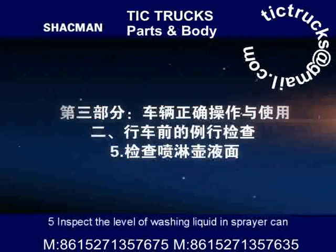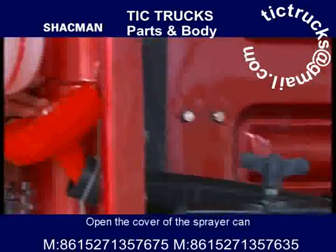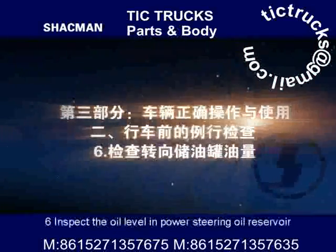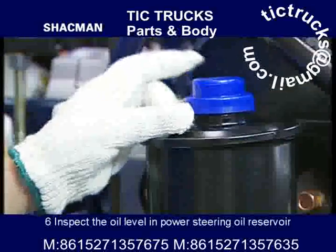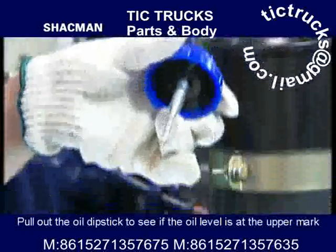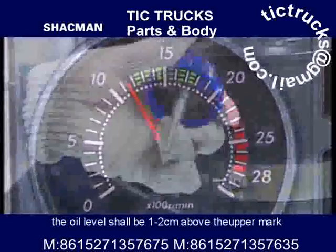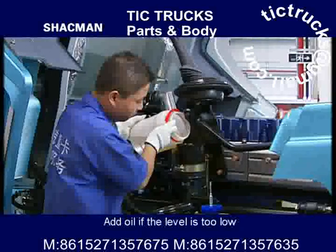5. Inspect the level of washing liquid in sprayer can. Open the cover of the sprayer can, check the level of washing liquid, and add liquid if the level is too low. 6. Inspect the oil level in power steering oil reservoir. Pull out oil dipstick to see if the oil level is at the upper mark. When the engine is running stably at medium speed, the oil level shall be 1 to 2 cm above the upper mark. Add oil if the level is too low.